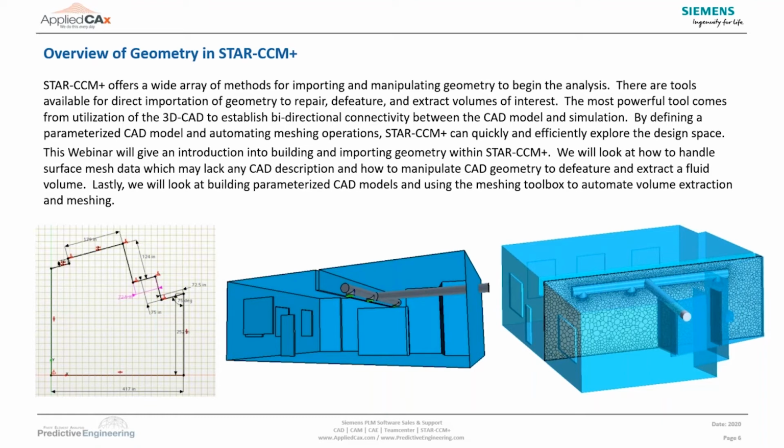There are powerful tools available within STAR to allow bidirectional connectivity between the analysis simulation toolkit and the 3D CAD. This allows you to make changes within the 3D CAD and automate rebuilding, remeshing, and rerunning the analysis.